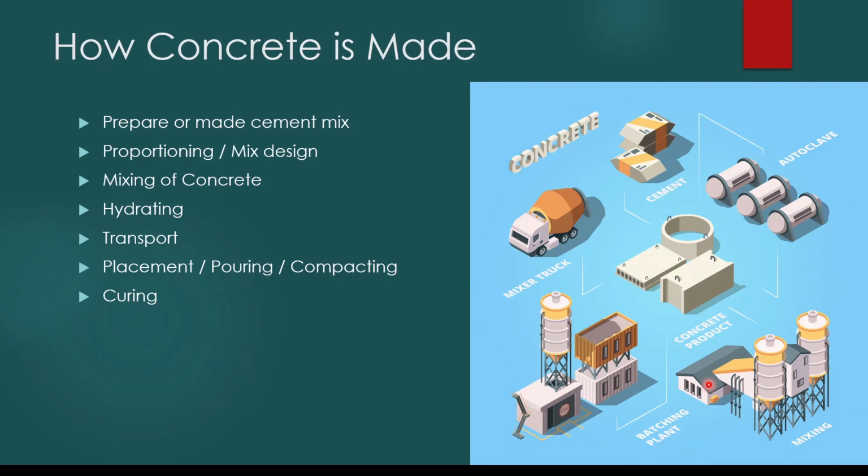It will affect the strength of the concrete. Likewise, there are other concerns like permeability, so many. Therefore, we have to do the compaction completely and correctly. Once you have done the compaction, you can level the concrete. That's it. After that, the laying of concrete is over.